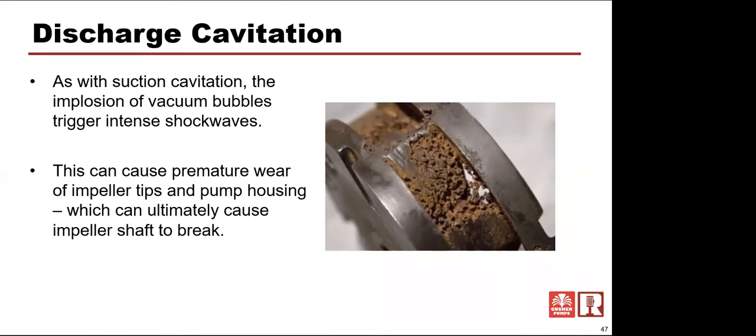So this particular impeller that is all pitted looks like maybe corrosion or something. Most people would look at that and say, well, my chemical must be attacking my impeller. You didn't give me stainless steel, you didn't give me iron or whatever, and it's some inferior material that's causing this corrosion. Well, that's not the case. This is suction side, or excuse me, discharge side cavitation that's trying to relieve itself and go back to the low pressure side. But in doing so, it causes so much turbulence that it causes pockets of very low pressure that then hit a higher pressure zone and collapse.